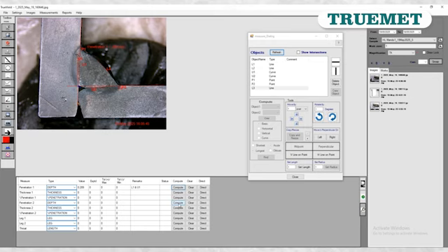Similarly, going to measure the penetration 2, that is L2 to U2. This is my penetration 2 distance. For thickness measurement, I am using a direct tool from here and going to measure the thickness directly, like here.